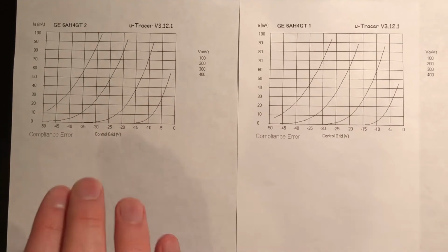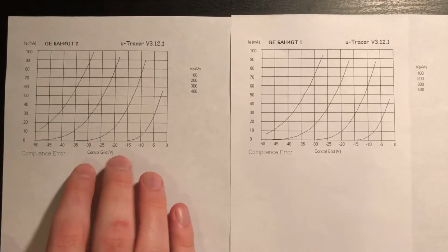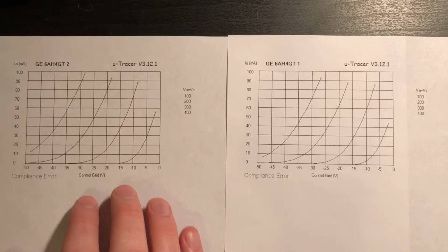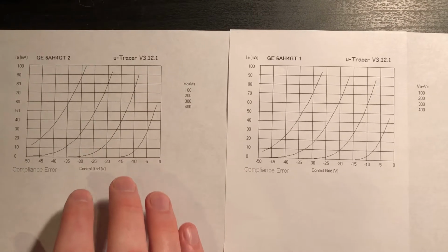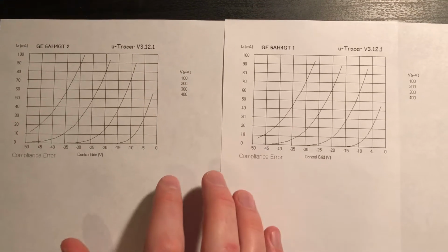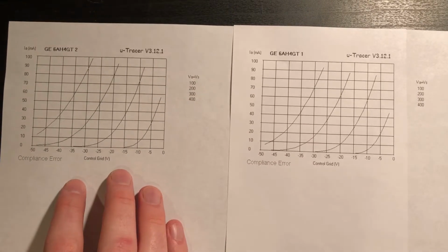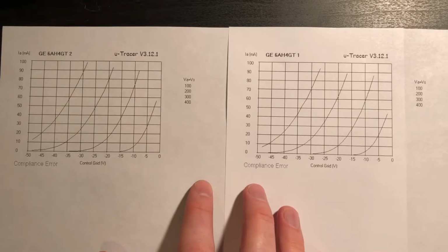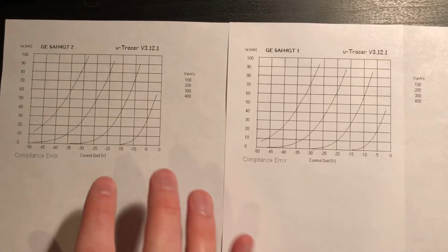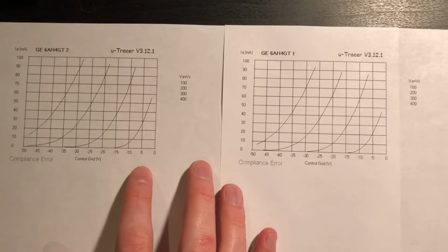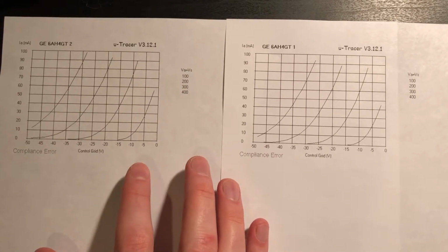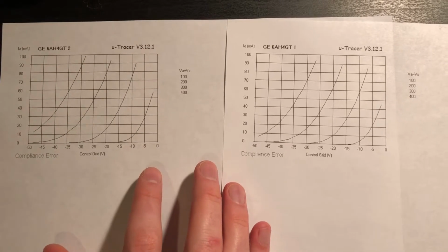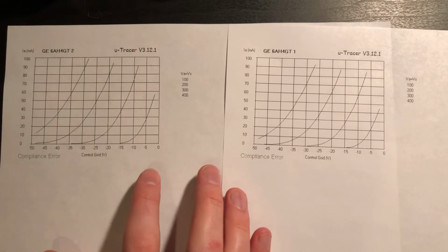As I've said before, I'll caveat that with this is measured with the AP, which may not be representative once we add our driver, and especially once we add our 844 output stage. We'll likely have more distortion cancellation because of the phase inversion as we're cascading these stages, and the impedance that the AP presents on these tubes is not going to be representative of a cathode follower, which will represent a much higher load impedance for this gain stage.